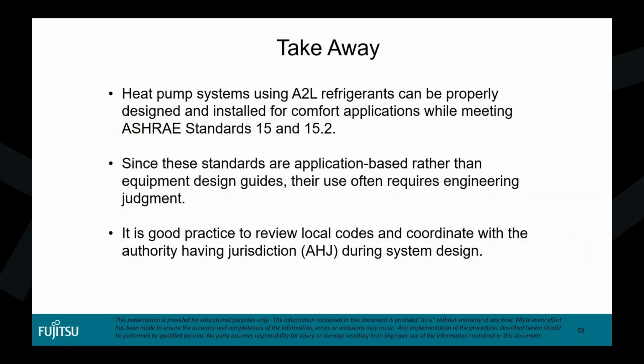So the takeaway, to me: heat pump systems with A2L can be used in almost all cases, in all applications. We saw that institutional occupancy could be a challenge. There are ways to design around that too, but the 0.5 there, multiplying the maximum amount by 0.5, could be a limiting factor.